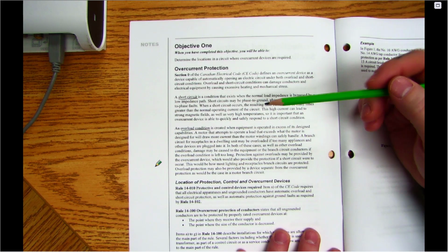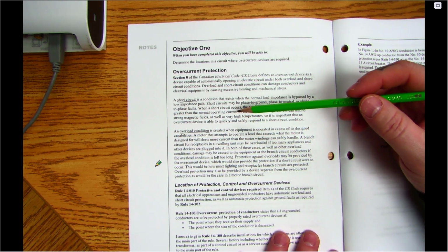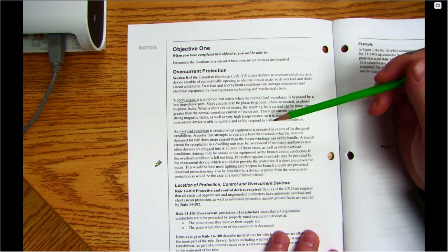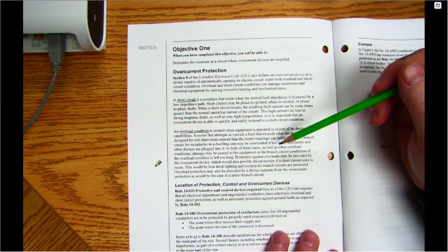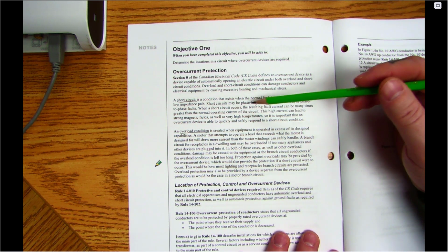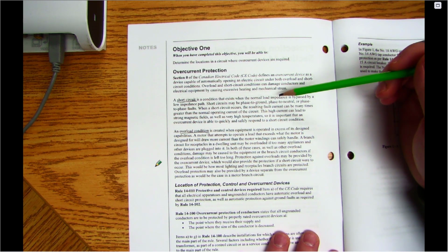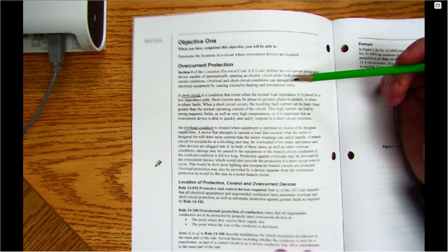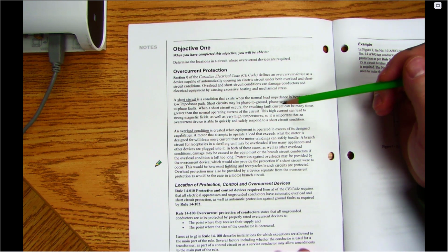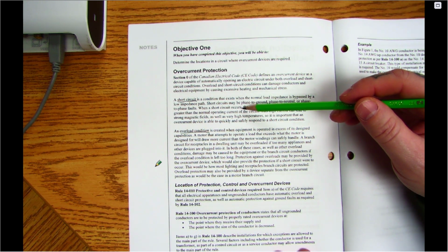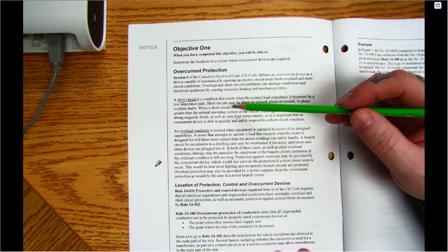So they go through first and do the definition of a short circuit. There's a difference obviously between a short circuit and an overload condition, and some forms of protection will do both, like a circuit breaker. Short circuit, again, line to line, phase to ground, phase to neutral. That's going to cause a short and going to be an extremely high value of current. It's going to create a strong magnetic field and a lot of heat, so we need to shut that down ASAP. But it's a lot of current we're going to see through there.